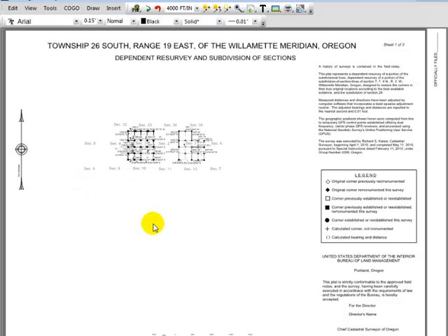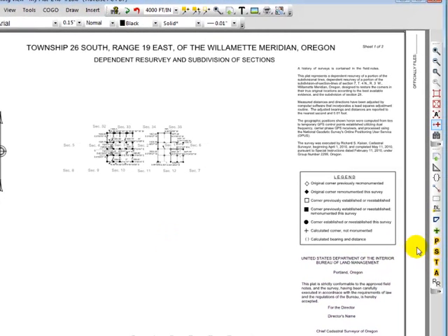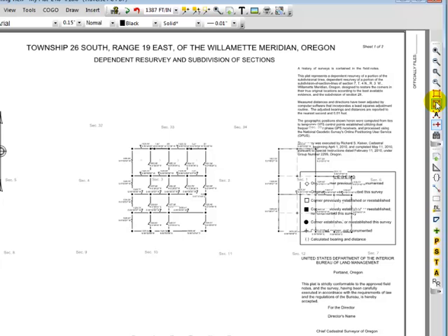Now, one of the things I like about Traverse PC's drafting is that if I come over here and highlight the survey space objects, do you see how they're in yellow now versus the paper space objects? Okay. So scale affects just the survey space objects. So I can tell Traverse PC over here on the right, I want to do a zoom extents, and it will fit those survey space objects onto the page for me automatically. Okay. So it scales it, positions it for me.